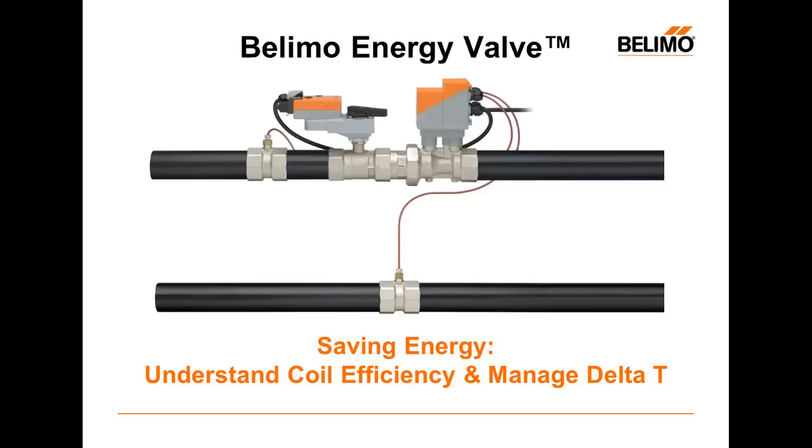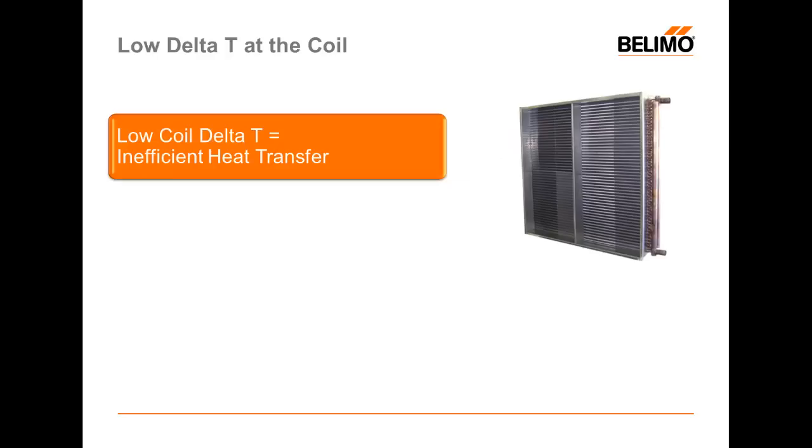Today we'll be discussing the Delta T manager and how it can save you energy. In order to understand that, we're going to talk a little bit about coil efficiency and how managing Delta T will save energy. Let's first talk a little bit about Delta T. Delta T at the coil refers to the difference between the supply and return water temperature from your coil.